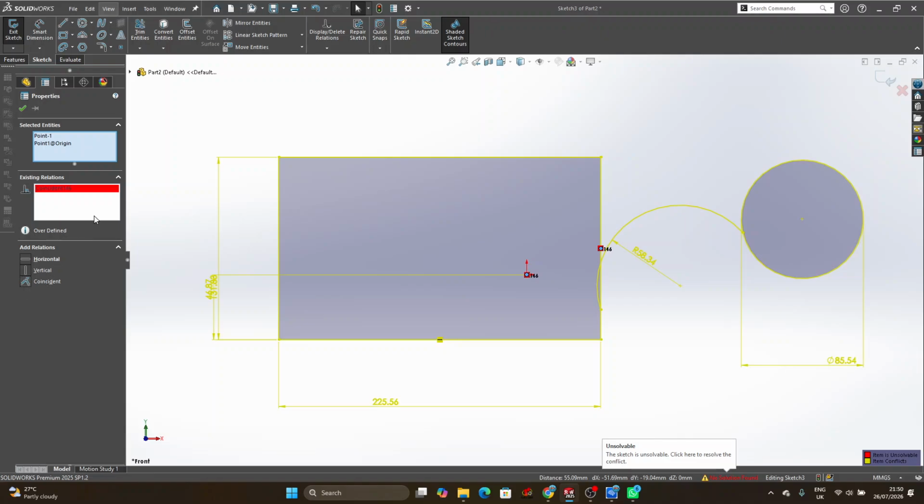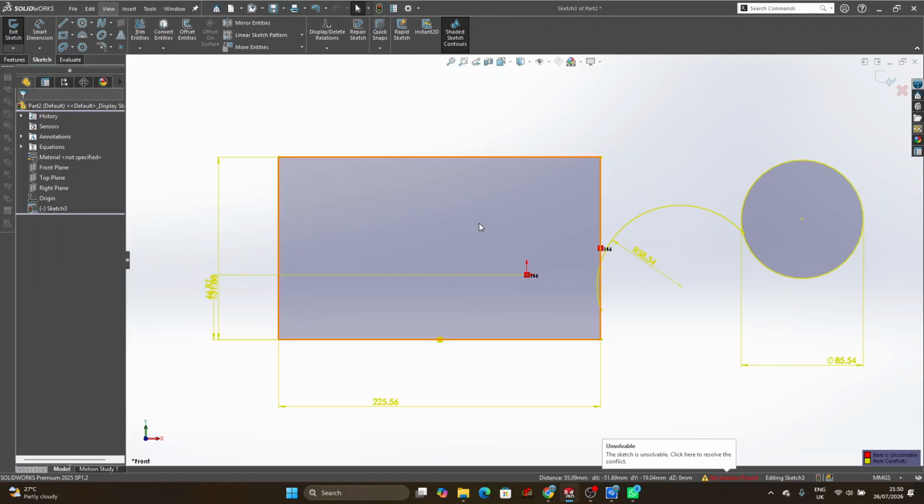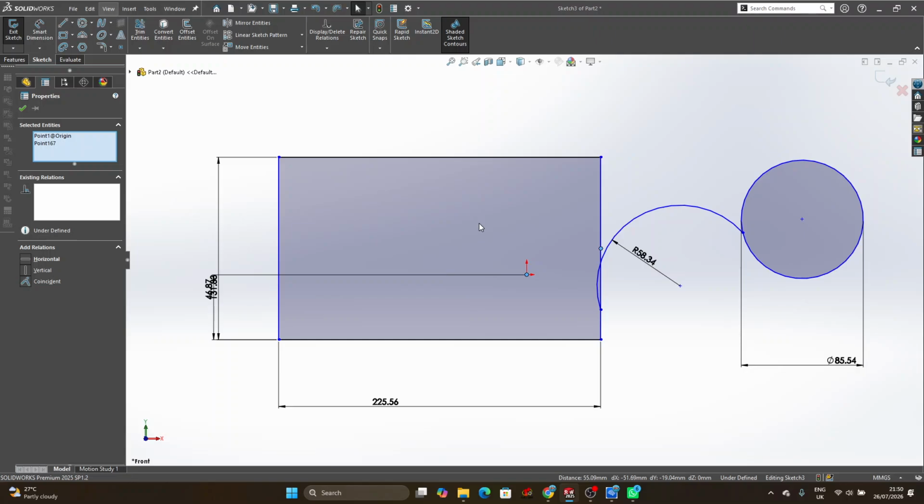No, it will show you an error because something is conflicting with each other, and I don't have time to explain that error now. We haven't really moved to explaining errors in SolidWorks. I'll still explain errors to you and how to rectify them. But for now, the error is showing because we have some conflicting relations there. So I'm pressing Ctrl Z to move back.